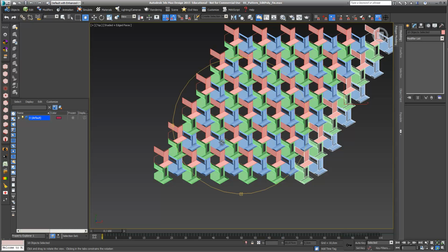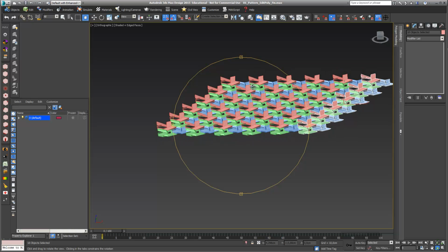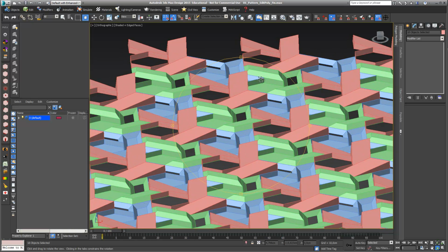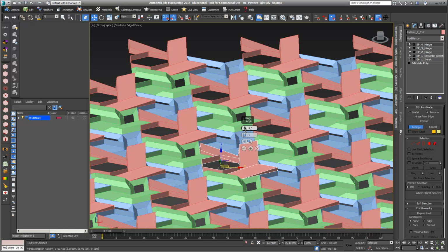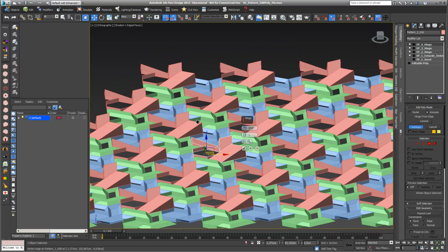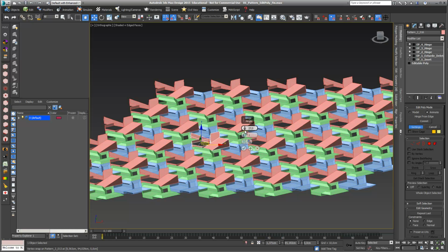What you can do is change it to perspective or to orthographic view. I just turn it like this. I can select any of these objects, for example like this, and if I go into the settings for my fourth hinge, we can see that I can change the angle, and all the other elements just follow, so the whole model is still completely parametric in a really nice way.